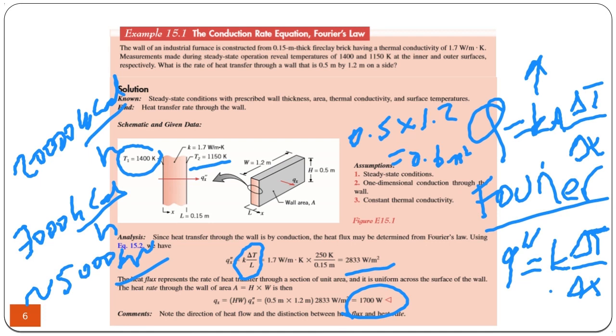So to keep the temperature inside constant, the energy that the radiator gives must be equal to the energy loss. So this 5,000 watts is actually the instantaneous energy loss from your house, and this is the calculation of the losses from windows, walls, ceiling, floors, and everything.